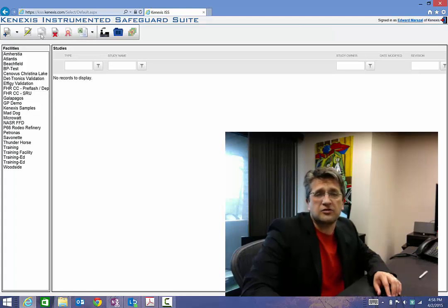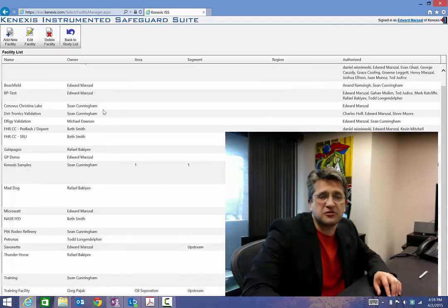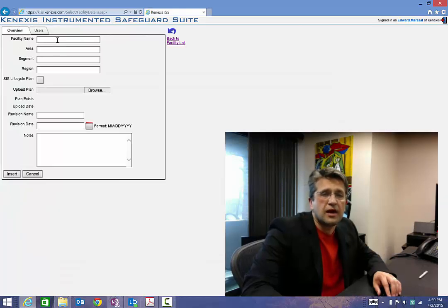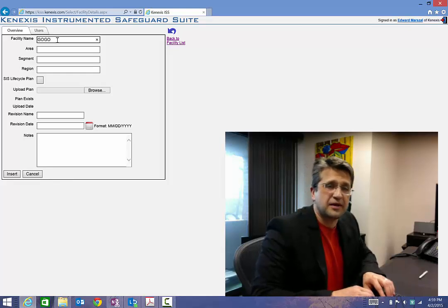I do that by looking at the action ribbon and going into the Facility Manager. When I click on the Facility Manager, it gives me a list of facilities that I can edit, or in this case I'm going to add a new facility. The facility name, I'm going to call it GOGO, General Oil and Gas Operating Company Chemical City Plant.